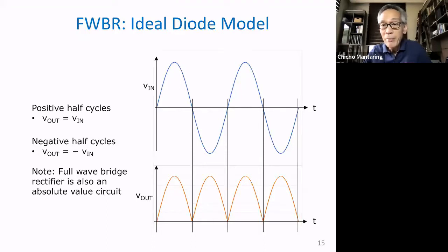So one way the manufacturer can avoid that mistake by the user is by putting a full wave rectifier. Meaning to say, no matter how you connect the battery, the electronic device will always receive the voltage with the correct polarity dahil merong full wave rectifier. Of course, it has some disadvantages.